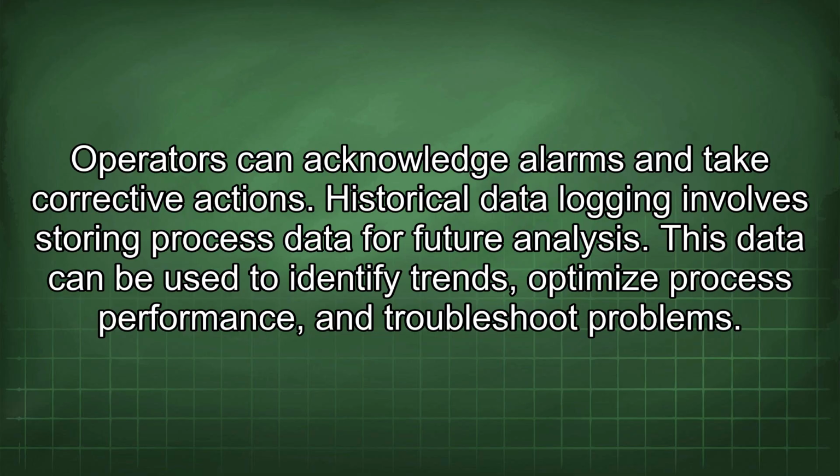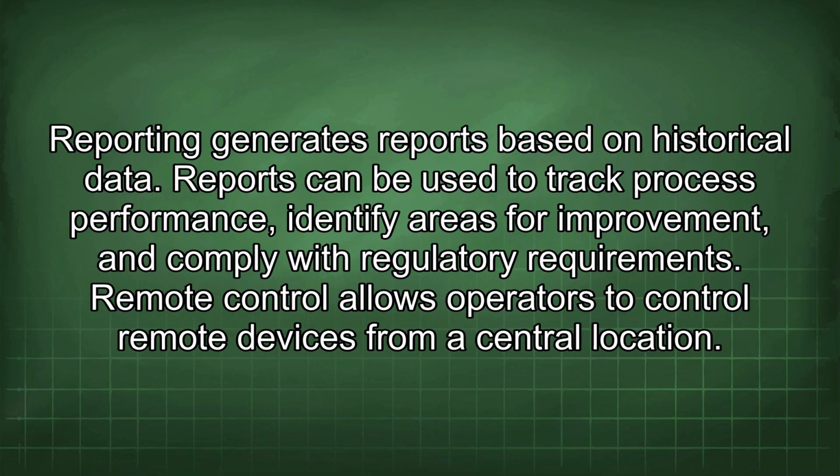Historical data logging involves storing process data for future analysis. This data can be used to identify trends, optimize process performance, and troubleshoot problems. Reporting generates reports based on historical data. Reports can be used to track process performance, identify areas for improvement, and comply with regulatory requirements.